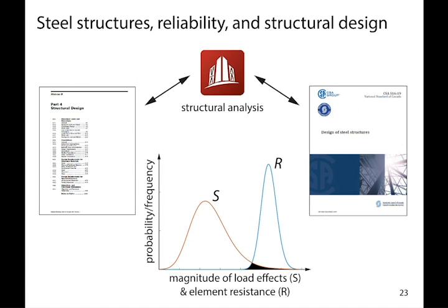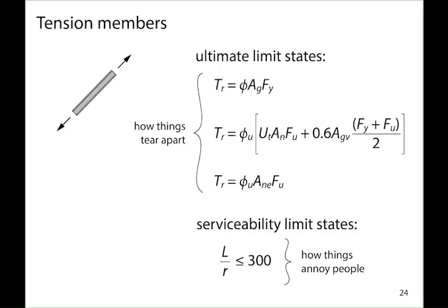I want to whip through a couple things quickly. When we're talking about the design of structures, limit states design, what I mean is we're going to calculate loads using NBCC. We're going to do structural analysis, and in this course, we're going to use a structural analysis software called STAAD. We'll talk about that more in the lab on Monday. And then we're just trying to make sure that the strength that we quantify in accordance with S16 doesn't overlap significantly with the load effects so that it's a relatively safe building with a low probability of failure. That's the philosophy that governs the structural design process in Canada.